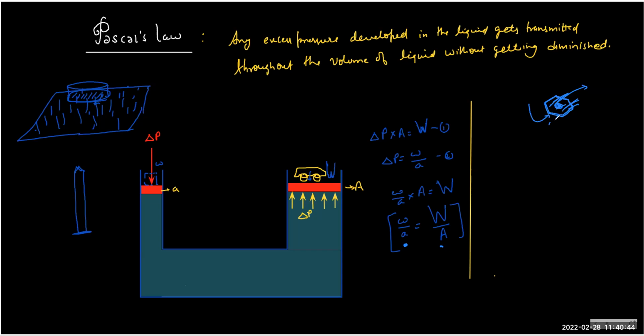Without the safety valve, pressure will build up, because the actual valve is kind of locked, because this is a tiny hole, and if some food grains get stuck here, the pressure will keep on increasing, and eventually if the pressure cannot leak out, it will just blow up the entire cooker. So the safety valve makes sure that beyond a certain pressure, this will open up and things will be in control. It will not create damage. So it is like the weakest link in the pressure cooker, and the weakest link is the safety valve. Okay, so I hope this is clear.